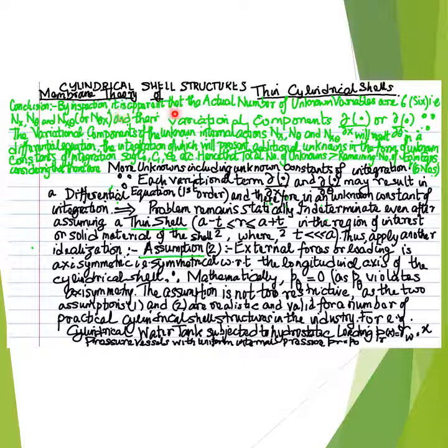which are or were found to be the in-plane or membrane actions nx, n theta, nx theta and n theta x, and the two unknown internal out of plane or plate actions qx and q theta.